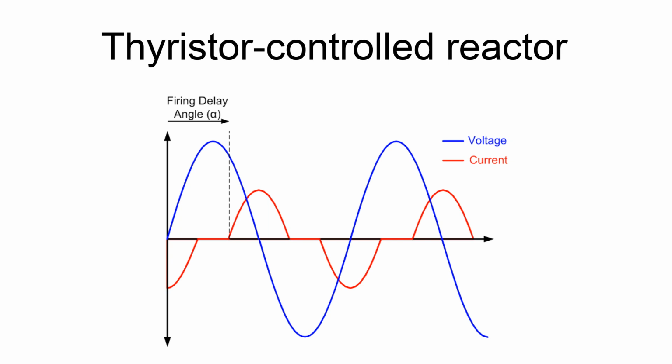In an electric power transmission system, a thyristor-controlled reactor, TCR, is a reactance connected in series with a bidirectional thyristor valve. The thyristor valve is phase-controlled, which allows the value of delivered reactive power to be adjusted to meet varying system conditions. Thyristor-controlled reactors can be used for limiting voltage rises on lightly loaded transmission lines.